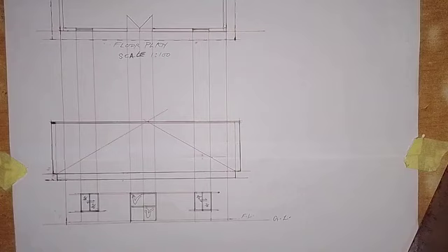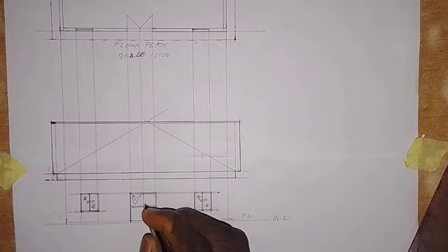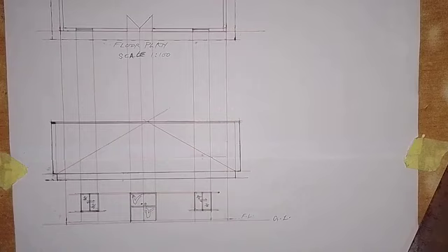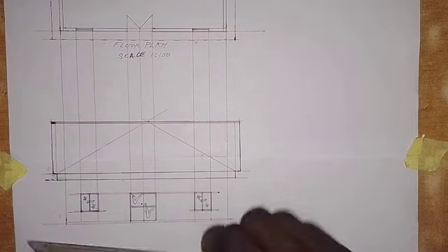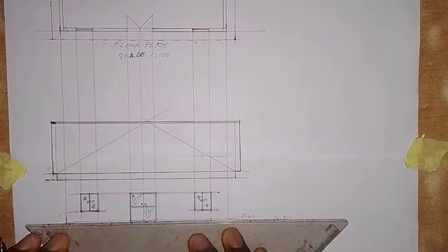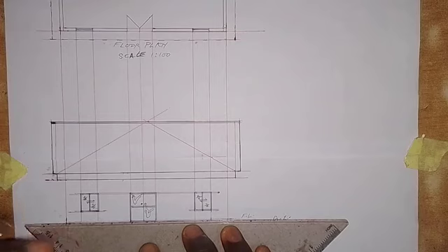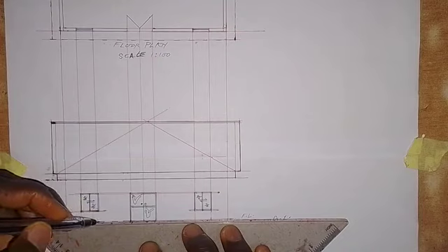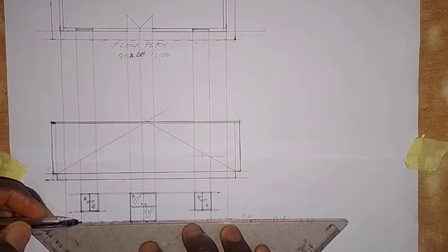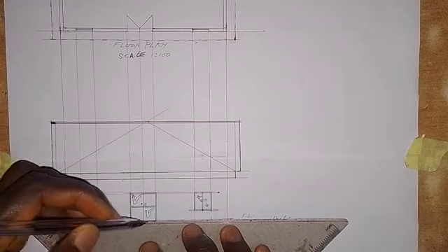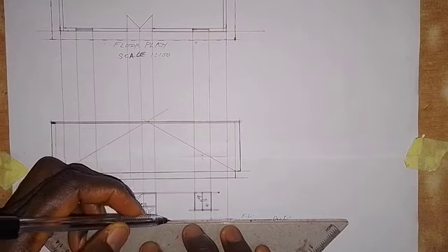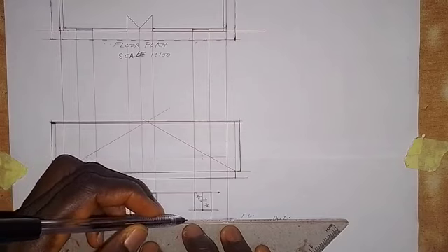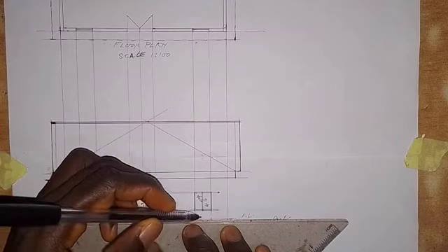All right, that is made of wood. I can just put something here like this for the lock. So we have completed the door. Now for the inner part of the building, this part here we can't see it, it is hidden from outside, so you have to draw it with a short dashes line, as we have here. This also we have to draw with a short dashes line as we have it here.